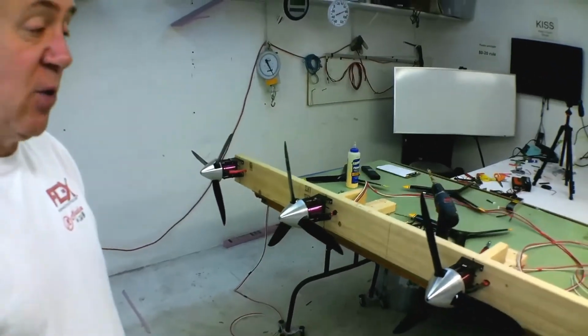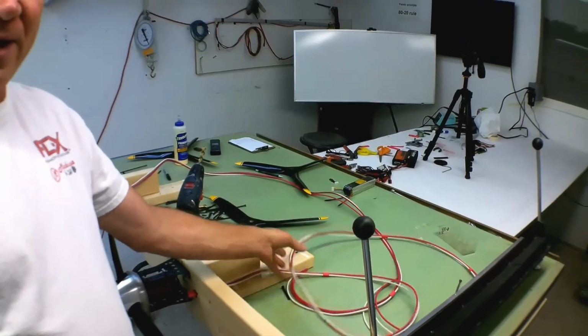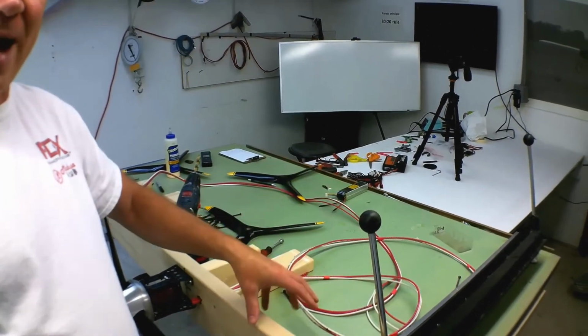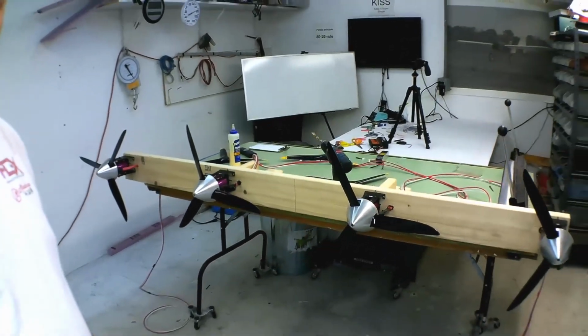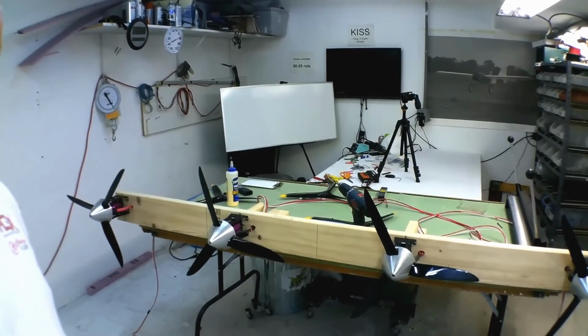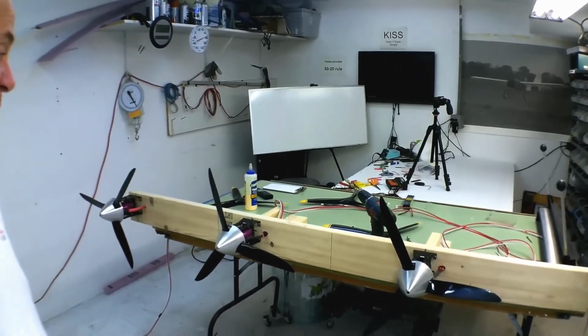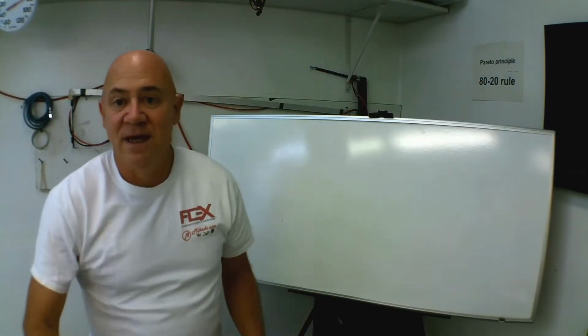So what I've done here is these are the actual lengths of wire that will be needed from the front of the airplane where the ESCs are back to the actual motors, okay? And before you start raising hell about lengthening wires, you can't lengthen the battery wires, but you can lengthen the ESC wires to the motors. So let's see, is this aiming pretty well?